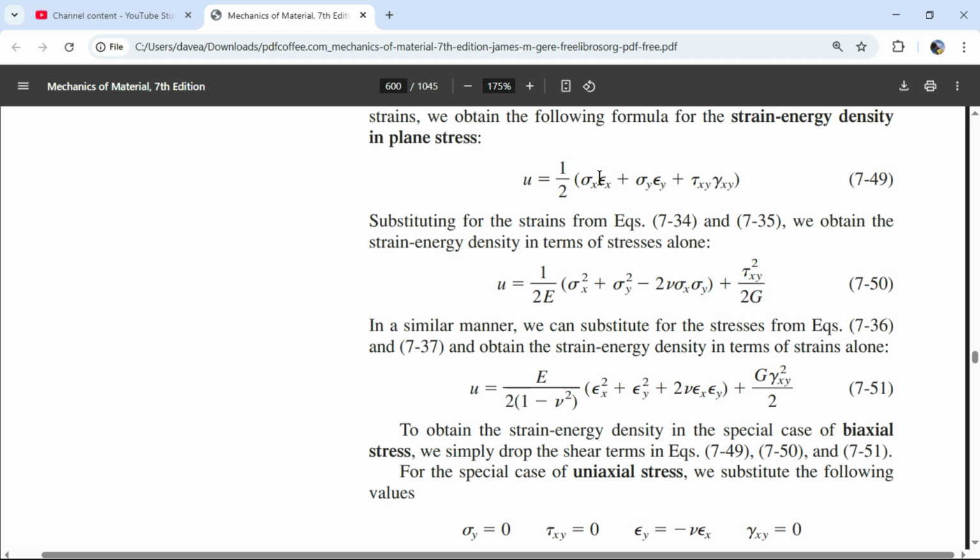And then when we multiply those out, we're going to have a minus Poisson's ratio sigma y times sigma x. So we get one of those terms. Over here, the change in length in the y direction is going to be associated with sigma y. So this equation right here is equal to sigma y minus sigma x Poisson's ratio, and that's it. And when we multiply those two together, we're going to have a sigma y squared minus sigma y sigma x Poisson's ratio. And we just have another one of those. So that's where we get this, just out of subbing those two in.